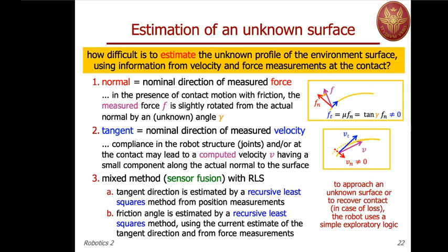From there on, you switch on your hybrid force velocity controller, or as we have seen, you may not need to switch this, because in the force control direction an impedance-based law can be applied also in free space.